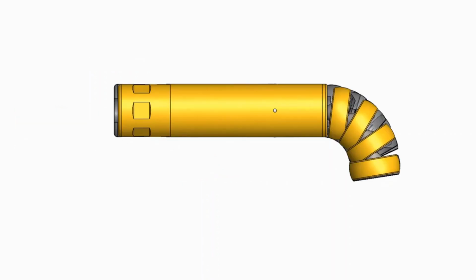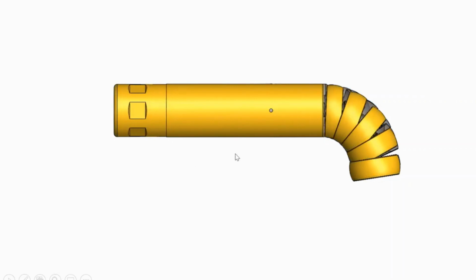We'll now use this animation to show the difference between the standard pitch mandrel, which is shown here. And once I click the screen, you'll see first the closed pitch, then the ultra closed pitch. So here is the closed pitch. And now here is the ultra closed pitch, and you can see where you have additional pressure points or load points to help support the tube, and the gap between the balls gets smaller.